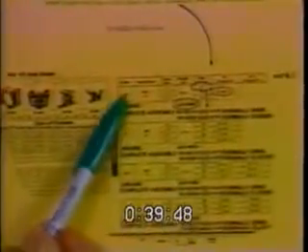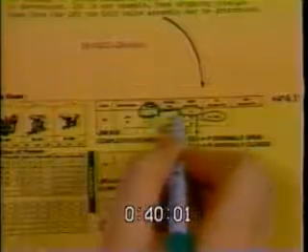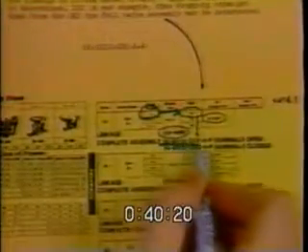The last step in finding the complete valve assembly number is as follows. We chose a series 200 actuator, which is right here. Notice it says stem up, and it has three ranges, 3 to 7, 5 to 10, or 8 to 13. We chose the 3 to 7. Going across from that, you'll see an actuator code number, in this case 201. Notice also to the right of that it says there's our actuator, the MK2690. Taking this 201 though and dropping straight down, right here is our complete valve assembly number.